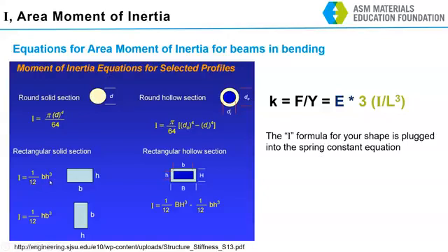So that skinniness of the beam in the thickness direction makes a big difference in this spring constant. Okay? If I flip my beam 90 degrees to go to what I was calling stiffness orientation, now the big number in my dimensions is cubed. So my force required to deflect the beam a certain amount goes up rapidly as I flip from diving board to stiffness orientation.